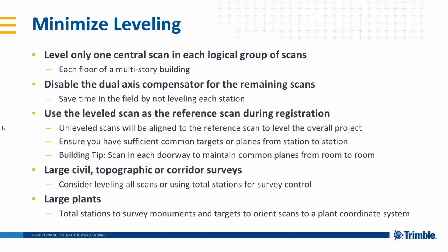And here's a quick tip for scanning buildings and using plane-based registration. You should scan in each doorway to maintain common planes when scanning from room to room. This will ensure RealWorks auto-register using planes will find enough common planes in your scans to automatically register.